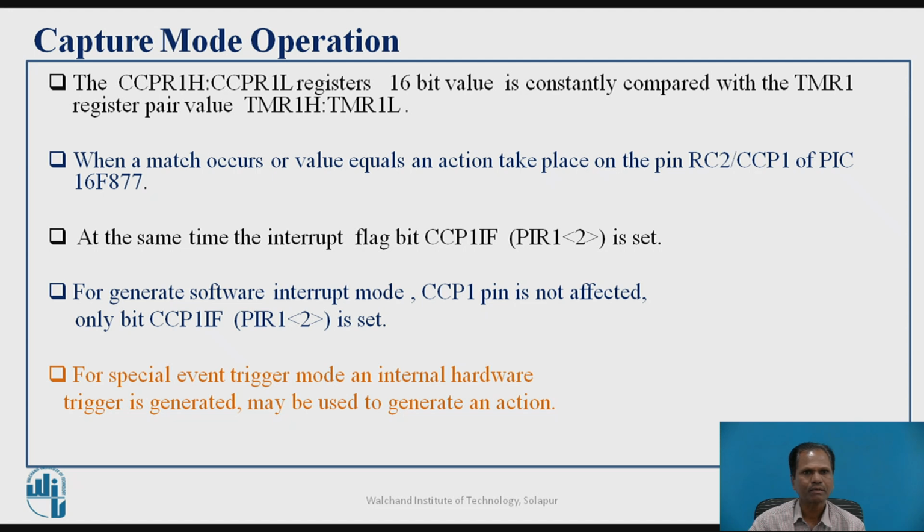For special event trigger mode, if the CCP module is programmed in compare mode for special event trigger, an internal hardware trigger signal is generated and may be used to perform an action.